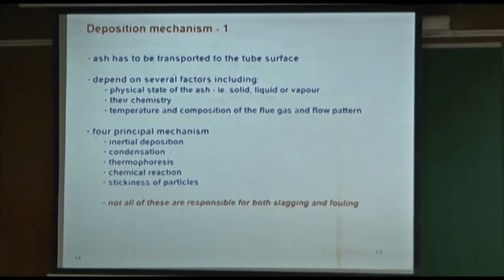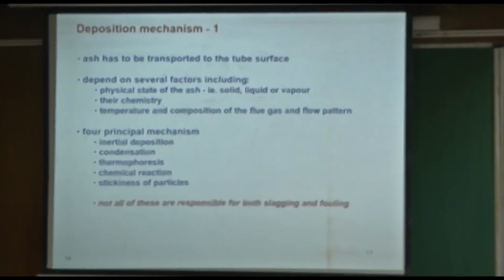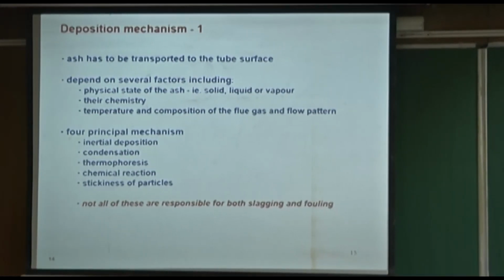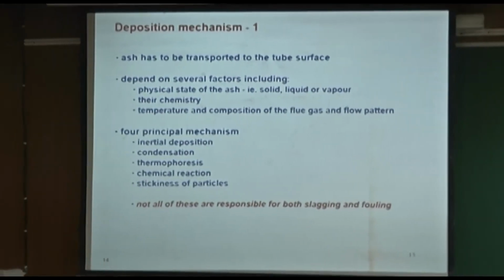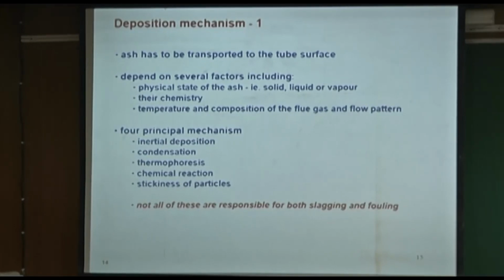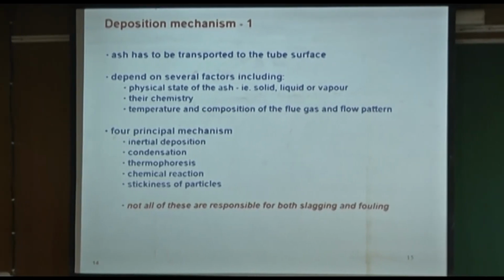This condensing, then the thermophoresis driven process, can aggravate it, and as a consequence, the temperature in the deposit, particularly at the surface of the deposit, will be increasing because it's not even able to give its heat away to the water. So chemical reactions, the mineral transformation reactions taking place, that's what it means.